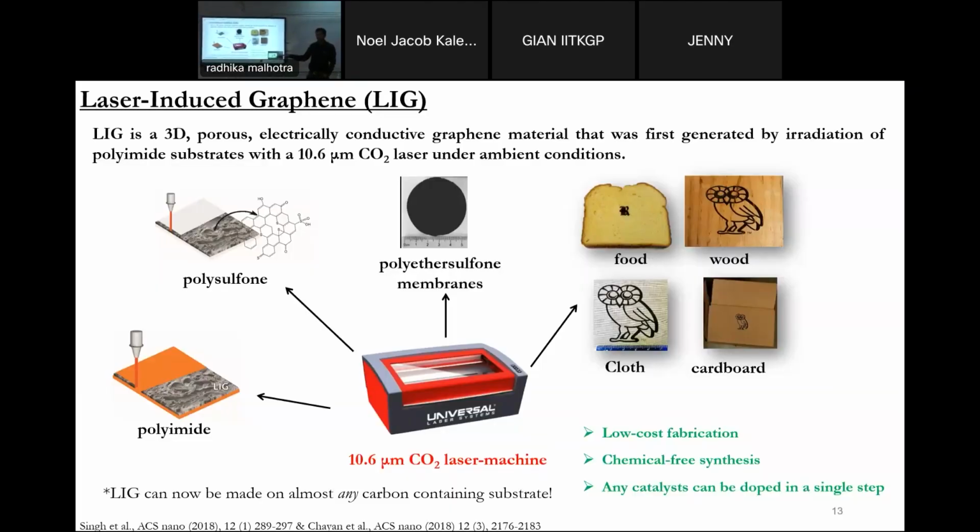But there is a disadvantage for the membrane process, which I will tell you later. If you take your ultrafiltration membrane, it can convert that selective layer, so then you will have more pores. It will open up the pores, and then you will lose the selectivity. But this membrane behaves as different functional membranes.